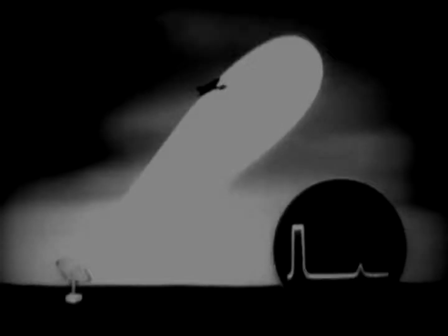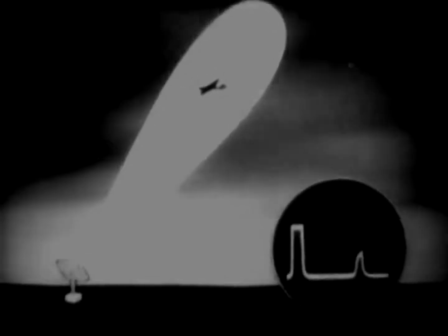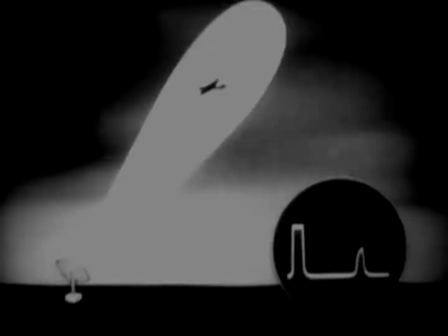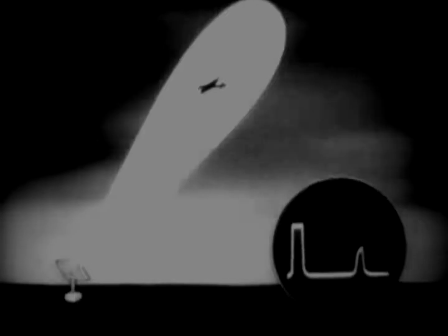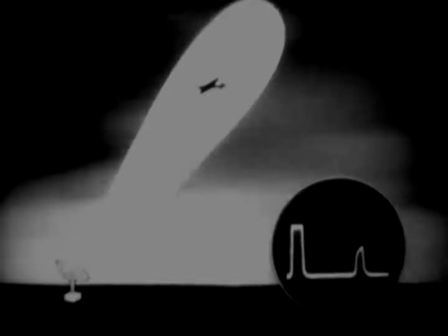As you traverse the antenna to catch up with the target, the plane is in a stronger part of the beam, and you get a stronger pip. It's the same on the other side of the beam. Minimum intensity, small pip. Maximum intensity, full pip, always letting you know when your beam is pointed directly at the target.